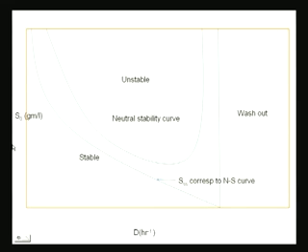One is S0, the initial substrate concentration I use, and the second one is D, the inverse of the residence time, or in other words, residence time itself. So what it tells me is what should be the size of the reactor, or size cum flow rate. Residence time is the ratio of these two, and the other would be my initial substrate concentration.